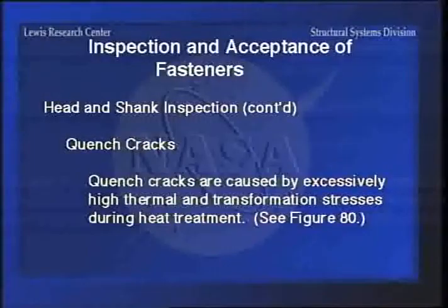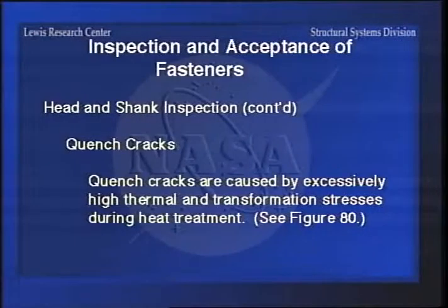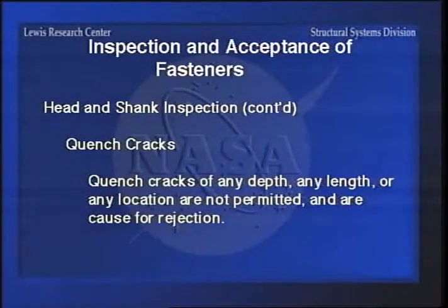Quench cracks are caused by excessively high thermal and transformation stresses during heat treatment. So getting one of those means that you've got problems with the material. So in general, quench cracks of any detectable size by visual inspection make the fastener unacceptable.